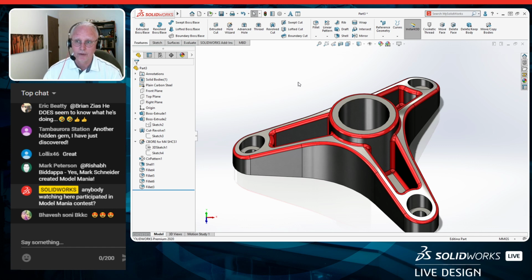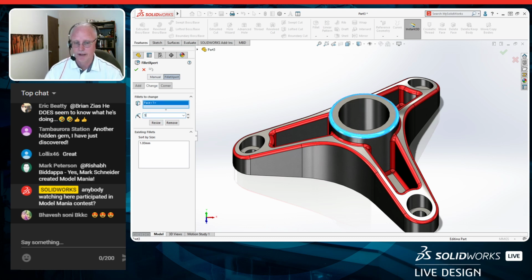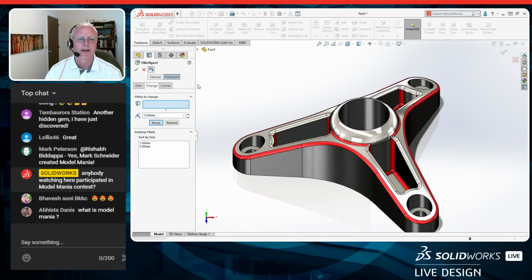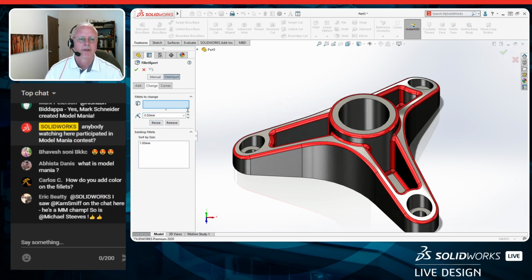Fillet Expert is really cool. You don't pre-select the fillet to make a change to, if you will. What you do is just choose the fillet command, go into Fillet Expert. You have this tab here that allows you to make a change. So what I want to do is change this fillet. I could change it to 5 and hit resize, and it'll change. I did something wrong there. Oh, I made it too big. Let's undo that. So I could change it to 0.5, resize. Oops, I didn't choose it. Choose this guy, and we'll say resize. So I can actually change that one fillet to resize it. Or I can choose this fillet here and then say remove. What that does is it removes it.